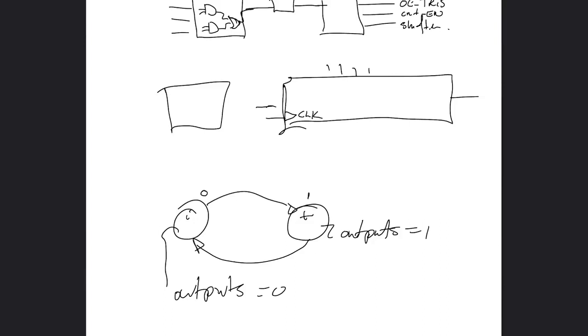And on each clock edge, it's either shifting through one position, or it's moving all 4 bits in at the same instant into the 4 flip-flops that I've connected here. That's how a shift register works. You control which one of those two it does by controlling something like a shift not load input. You can also invert that logic if you want, but this makes it a bit simpler. So we're saying if that input is low, it's just going to load all this stuff in.